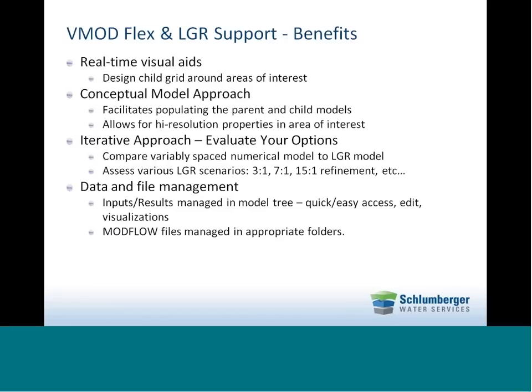Some of the benefits of how we've provided support for LGR in VMod Flex are as follows. The first is that you have real-time visual aids when you're designing the child grid. When you're specifying where you want that child grid to start and end, you can add any appropriate data objects, whether they be well fields or geological features, to help you position where that grid should be. The conceptual model approach dramatically facilitates populating the parent and child models, so you don't need to worry about whether your shape file should be translated to the child grid or the parent grid. This is done for you automatically once you build the conceptual model in VMod Flex.